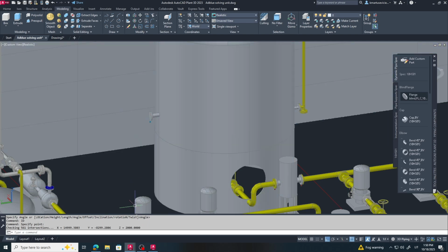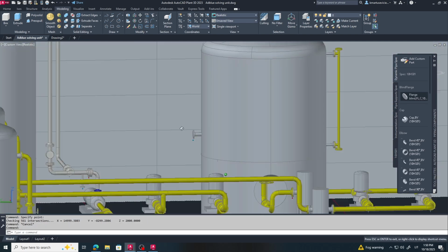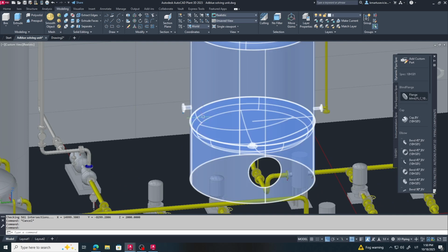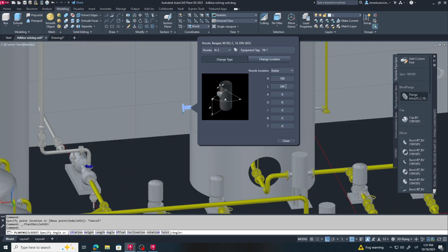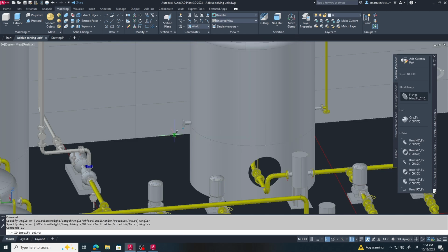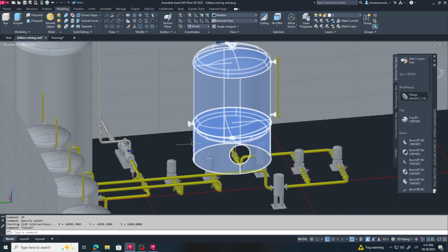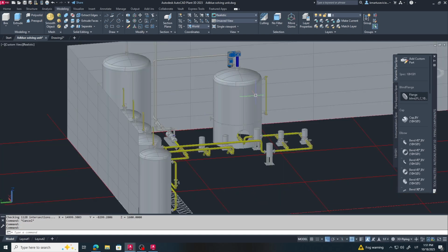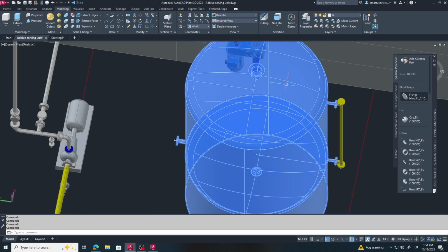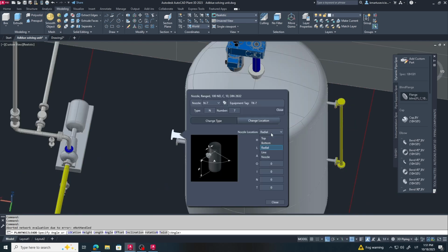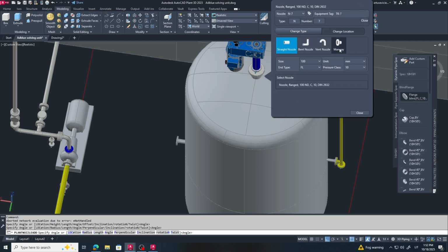The reactor also needs a refractometer. A refractometer is an inline instrument that measures the concentration of a liquid by analyzing how much it bends or refracts light. In AdBlue production, this is very important because the final product must reach a precise urea concentration, typically 32.5%. By installing a refractometer on the outlet line or on the recirculation loop, we can continuously monitor the concentration in real time. This lets the operator adjust water or urea dosing immediately without taking manual samples.